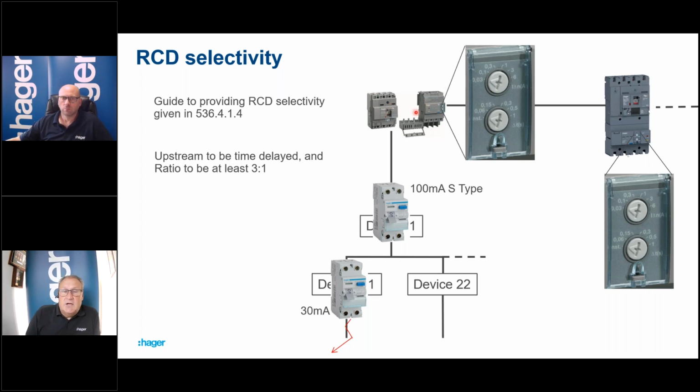Now, once we get to this type of level, we usually have adjustment settings. So here's the magnified version of the adjustment screws on this RCD add-on block for this MCCB. Now, the adjustment options usually are time and current. So we have adjustment of current at the top here, I delta N in amps.